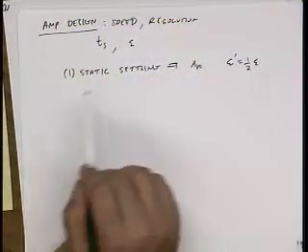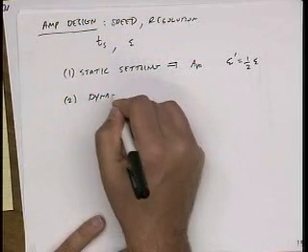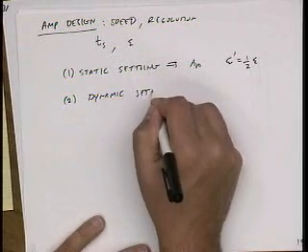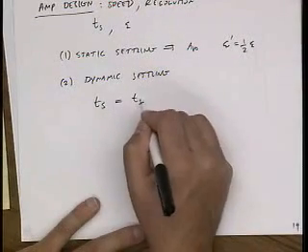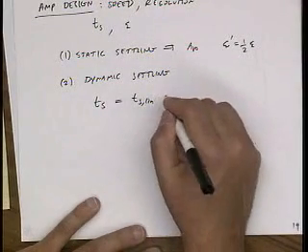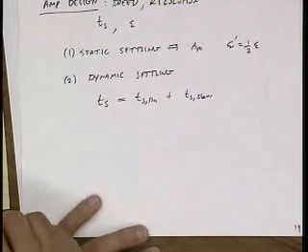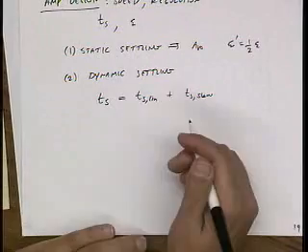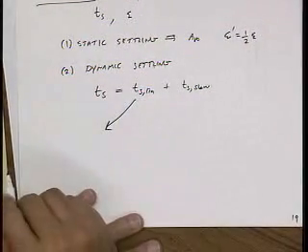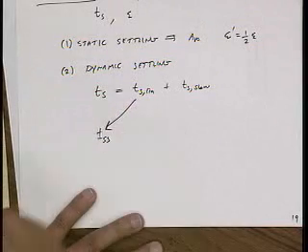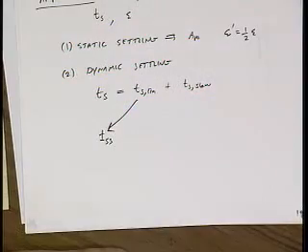A static term and a dynamic term. The dynamic term also, we found out today, has two components. It has linear settling time and it has a nonlinear settling time, right? And the idea is that we know from our calculations that settling time is just directly proportional to current. If I want to settle faster, I just have to burn more current.